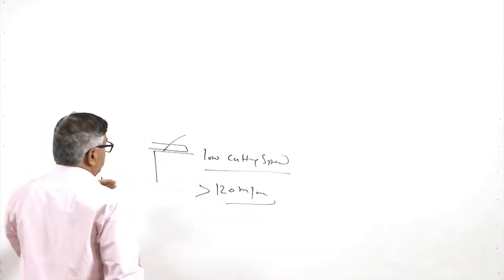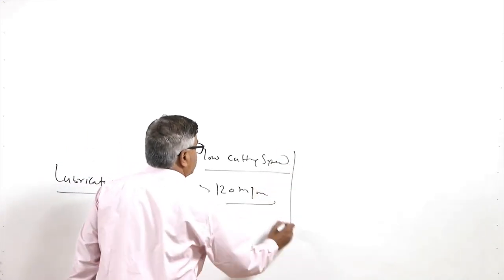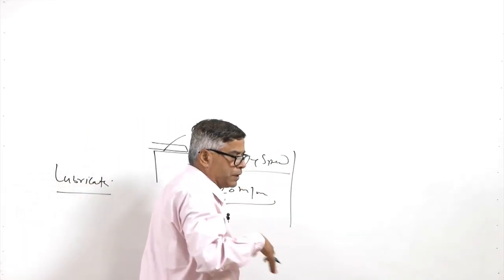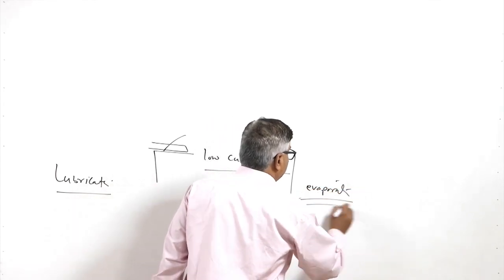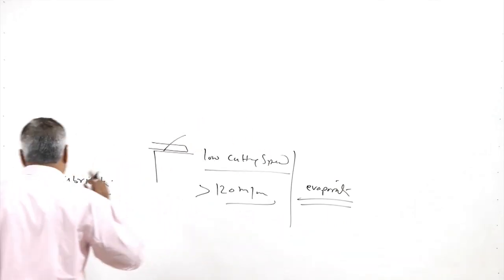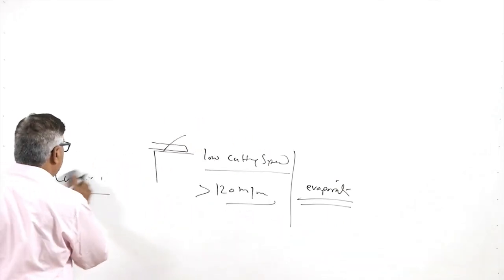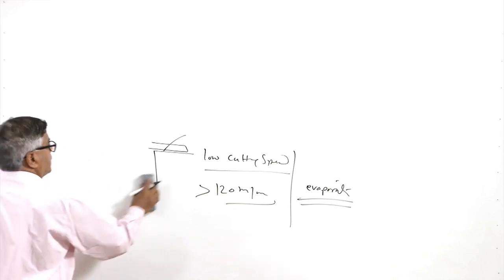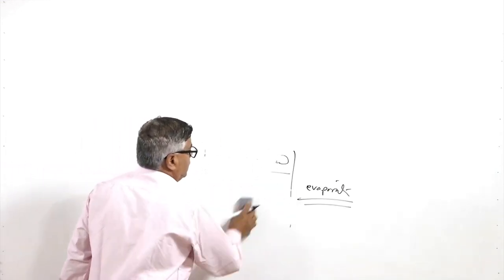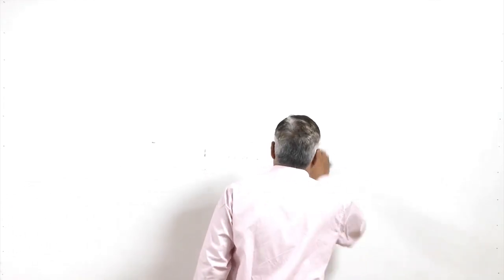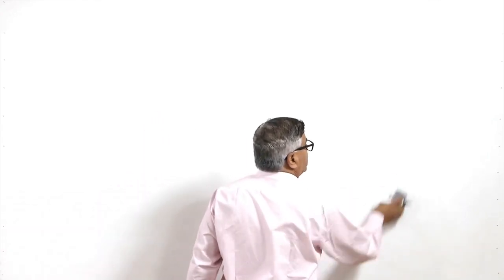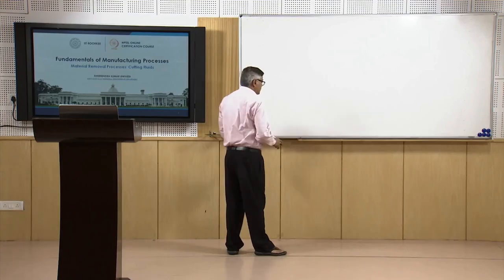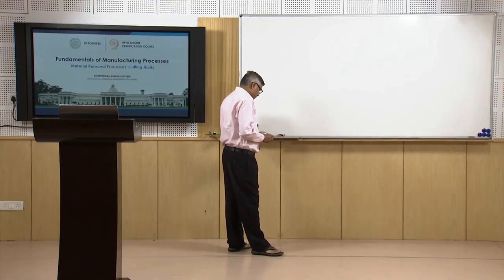So, the lubricants will not be able to perform their functions. As well, under high speed conditions, whatever heat is generated leads to the evaporation of such cutting fluids. So, at high speed conditions, lubrication based cutting fluids do not remain effective, and that is why we need cutting tool material having stability even at a high temperature to deal with those situations.